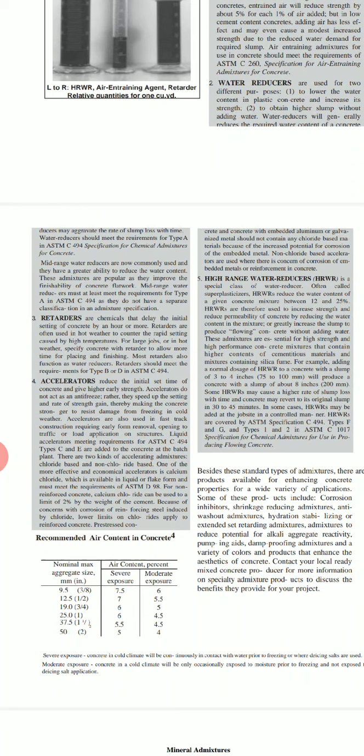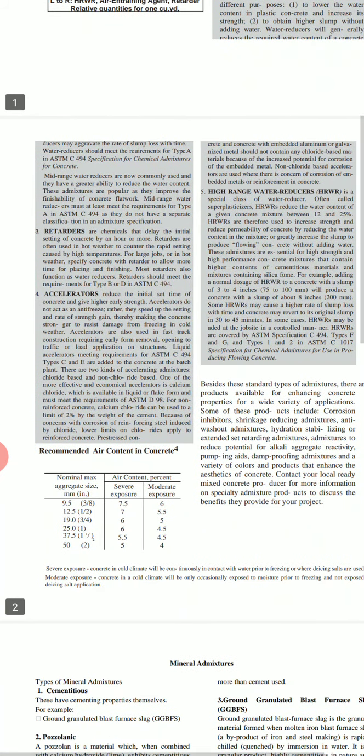Okay, as you know, it absorbs the water and reduces the setting time. So sometimes retarders will also act as water reducers, and they should match the specification of ASTM C464.